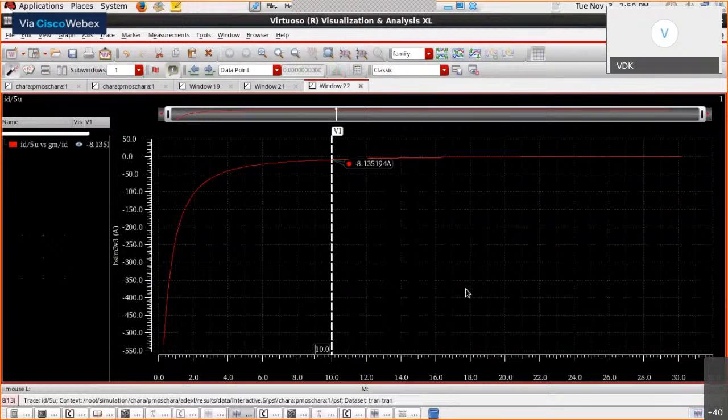All right, so I guess I answered the query: how do I fix things if I have more transistors? This becomes clearer as we go to the last circuit, that is designing an operational amplifier, straightforward. But there, we don't look at the gain value, we are going to look at the bandwidth requirement. So we again use the same approach, but our parameter of interest is the unity gain crossover frequency of the op-amp, apart from its small signal DC gain.